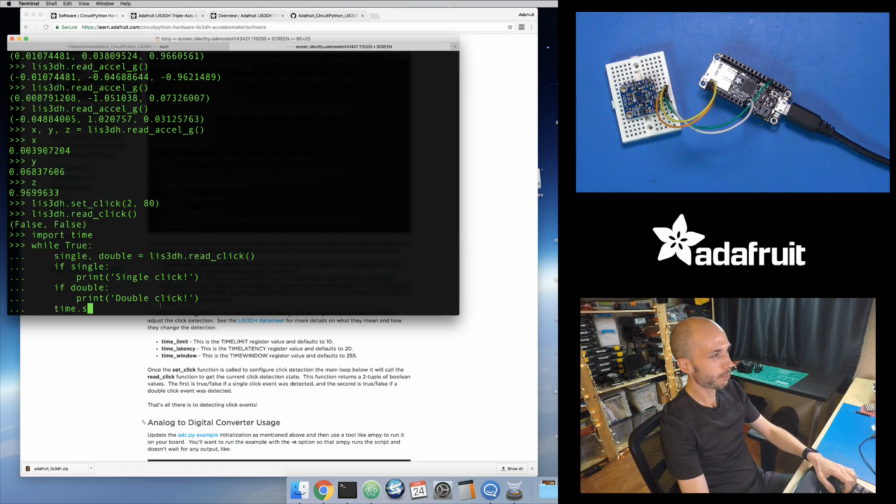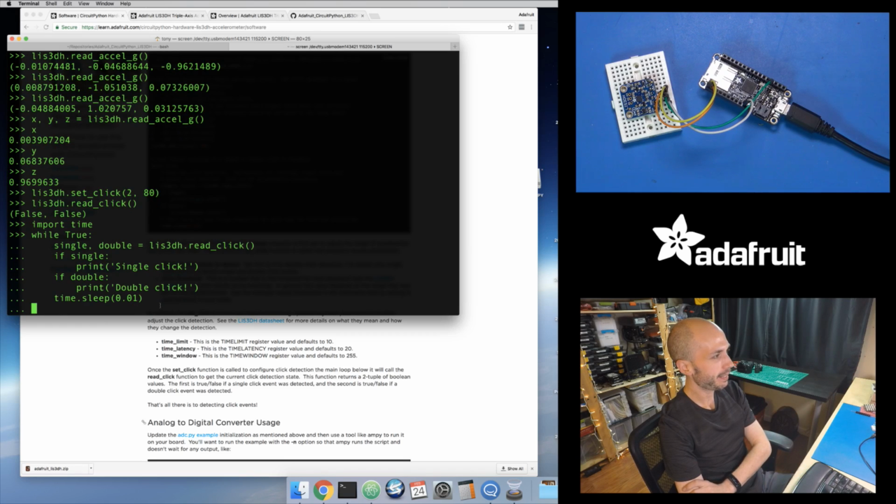And then I'm going to give it a small sleep because I want to give some time back to do any interrupt processing. Usually you don't want to do an infinite loop that doesn't have any sleep inside of it, because sometimes there's interrupt processing and things that happen in the background. So like a little maybe 10 millisecond sleep makes sense to do here. So I'll do that, and then we'll let that run.